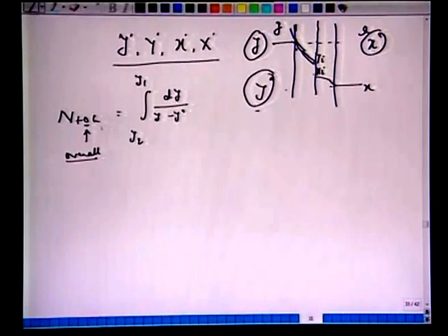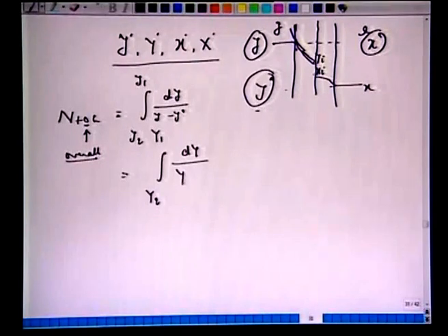So, we can also define NTOG, instead of NTG, working on y star instead of yi, or if you want to work on solute-free concentrations, capital Y1 to capital Y2, then this becomes dY over Y minus Y star. Analogous to this we will have HTOG, which can be written as G prime over capital KYa.